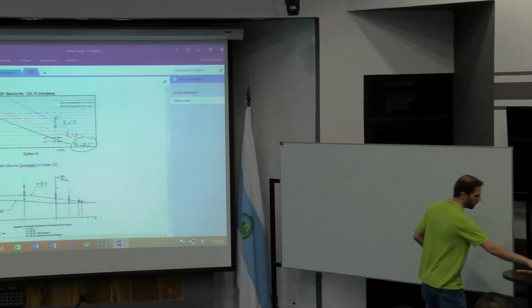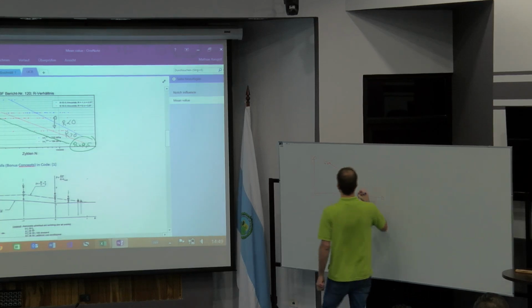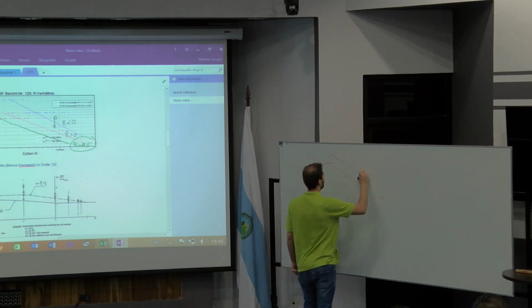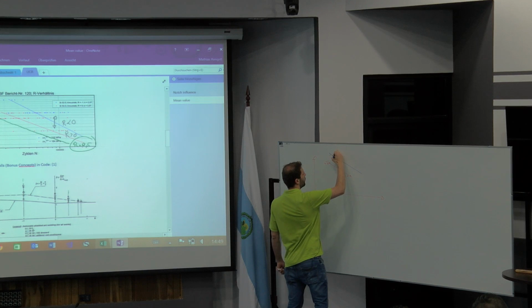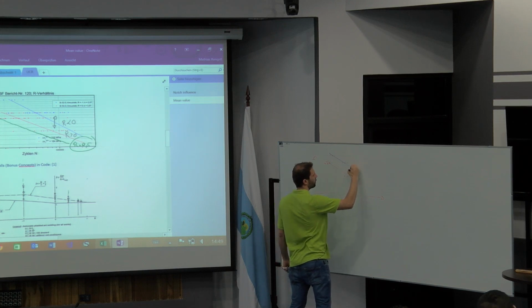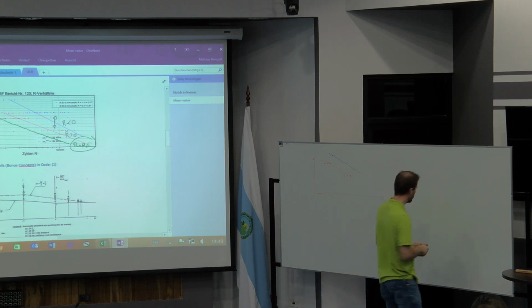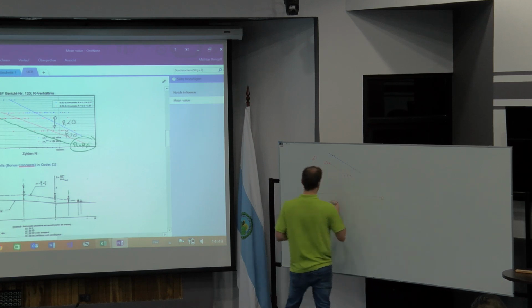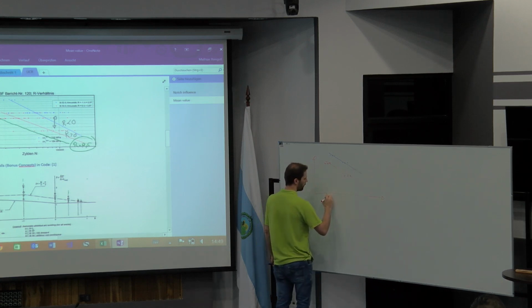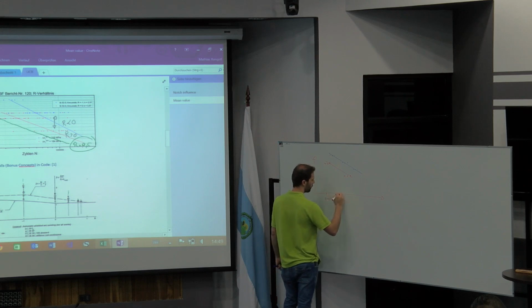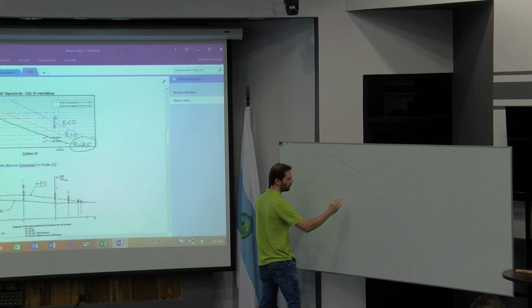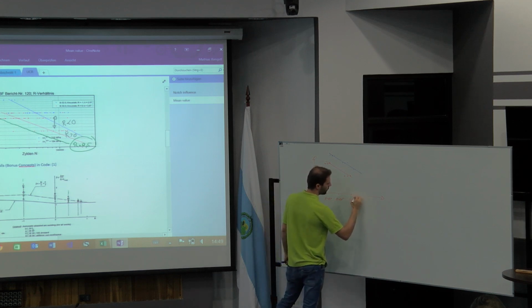And at the same time, we can do it as we have here for a second R value of the same specimen, of the same welding. And at the end, you're just going to evaluate the values at specific numbers of cycles, like N 10^4, 10^5, 10^6, 10^7.